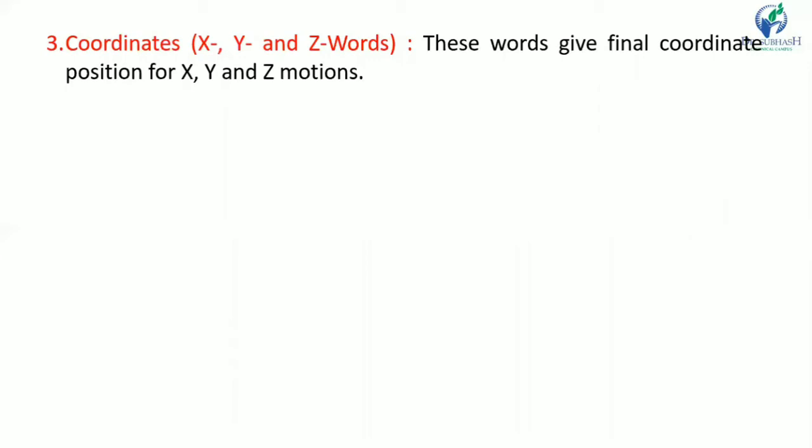That is, X is equal to 5.60 will be written as X 0000560. Okay, X 5.60 will be written as X 0000560 in a particular system where X dimension is to be followed by 6 digits, and the control system places the decimal after leaving two least significant digits.